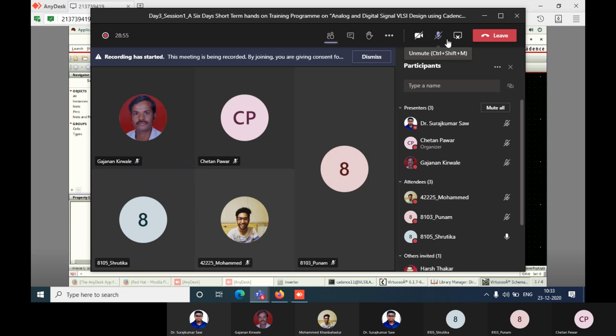Okay, fine. Yes Ritika, go for the power analysis. As I explained in the first class, that output, save all, right? Go add power here, average power. Save all. Click on save all. Yes, save this and this. Right? Apply, OK. Now you run this ADL again so that power will be loaded.